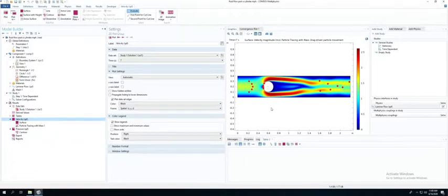All right, and what you did as part of your tutorials is that you had to change the diameter, or the size, of this stationary object inside of the pipe. You just increased it or decreased it or moved it. You made this different. So let's say that I wanted to see how that affects the velocity of the flow through my pipe. Maybe I wanted to look at the average velocity in this pipe and see how it changed with the size of this stationary object.